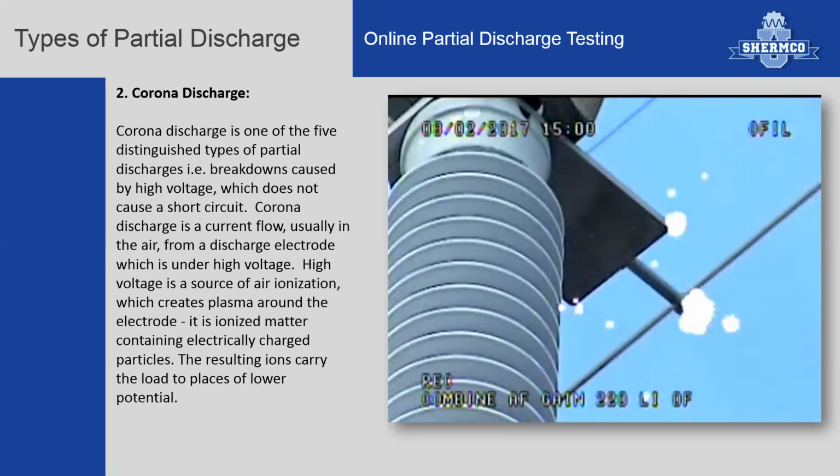Now, the development of ultraviolet radiation detectors or corona cameras have become very, very useful tools. And we'll talk more about them when we talk about sensors. But prior to the ultraviolet radiation detectors or corona cameras, one of the methods of determining corona coming off of substation equipment would have been the use of ultrasonic acoustic air-based detectors, which again, we'll talk about in a little bit.